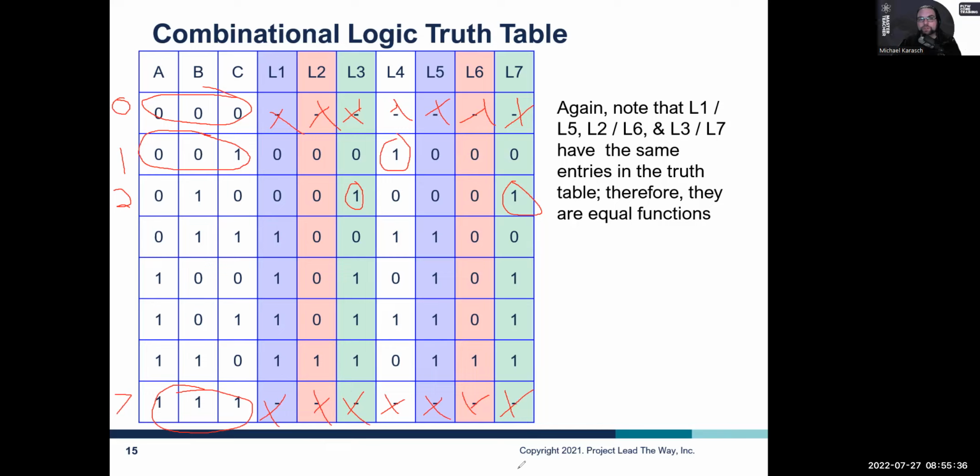And boy, it becomes really real for you and for your kids, because they're like, if I spend 5 more minutes in the design process, I can save myself 2 hours of breadboarding because I eliminated 4 chips and all these extra wires. Like, it becomes very real. Not to mention from a commercial aspect that every chip you save is money. Every chip you save is less battery drain. It's less heat that we have to deal with. It's less chips the factory has to stock. It's less solder points. It really cascades how important it is that we eliminate as much complexity as possible.